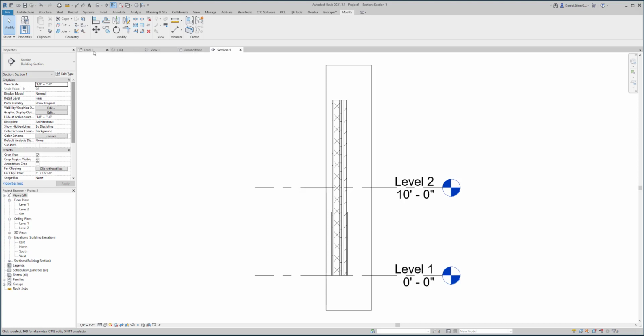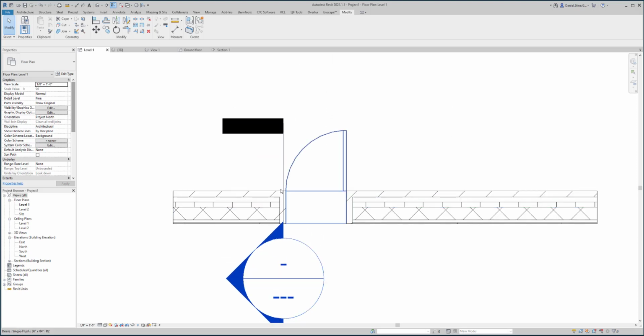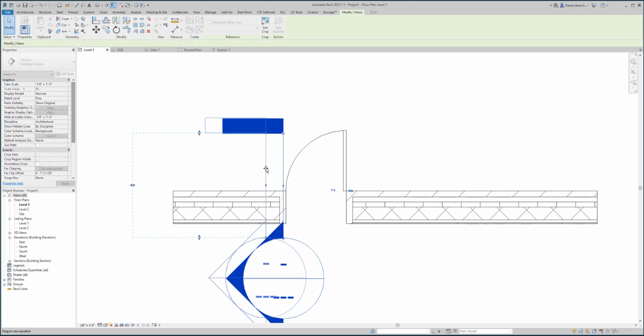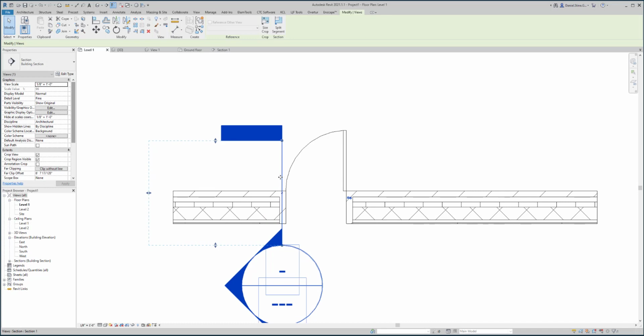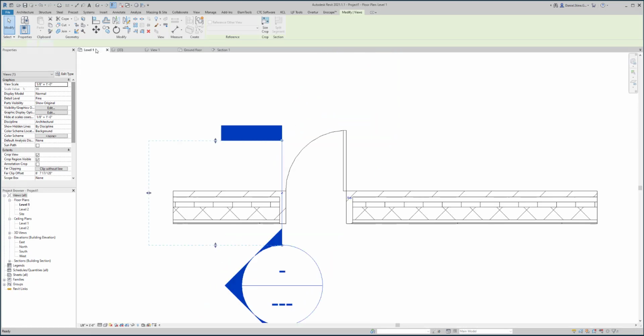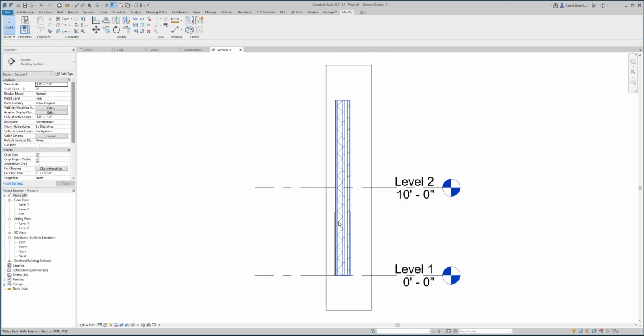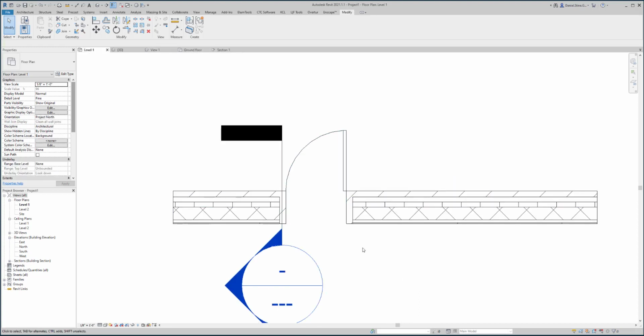One thing that's sort of interesting, these layers in the walls aren't technically really fully 3D. So when I cut a section directly through this return, it doesn't look any different than here. So really what we're seeing in these different views is an overlay to the overall wall thickness geometry. It's not really 3D elements within the wall. And that's why this section would be solid brick based on where I drew it in plan. So that's the only caveat you have to keep in mind.